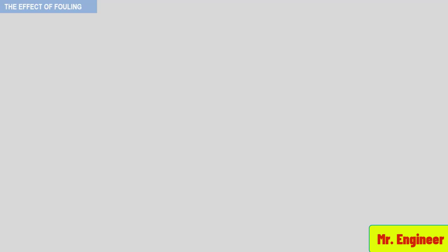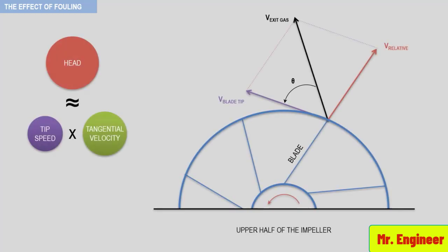So far, we have investigated the cause of the compressor curve, that is, the method in which head is produced in any impeller. Recall, head is produced by the change in two velocities, namely the difference between inlet and discharge velocity relative to the blade, and the change between inlet blade tip speed and discharge blade tip speed. In this section, we will explore what will happen to the energy production or head production of an impeller if that impeller were to change in area.